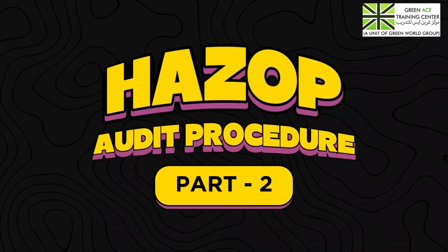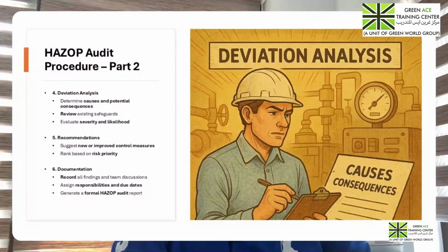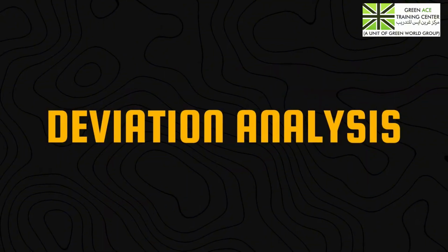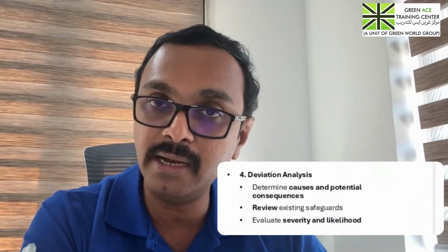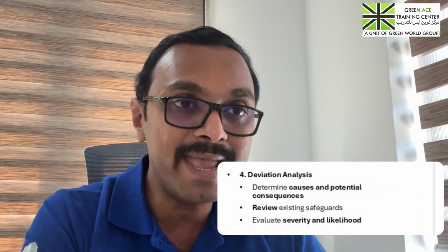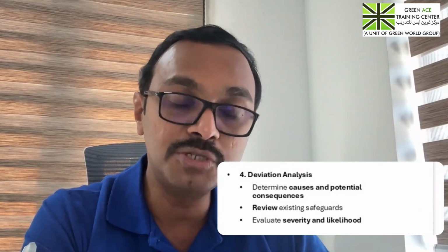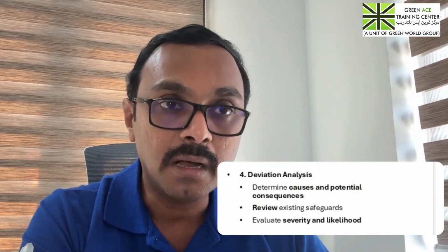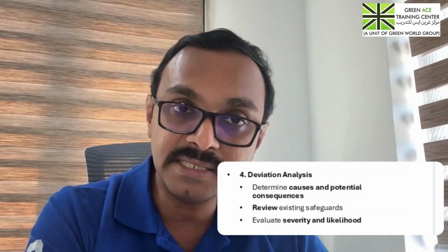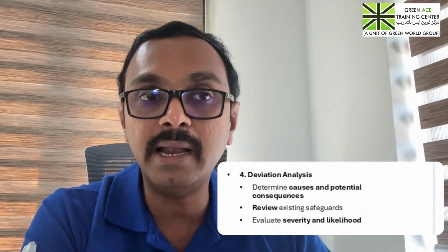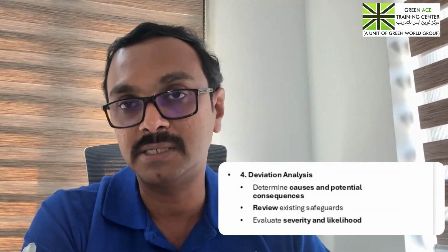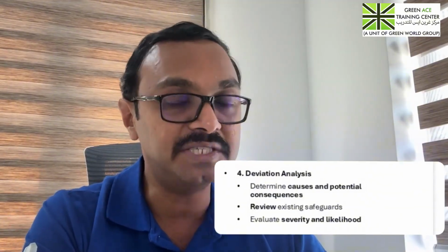Now let's go to part 2. In part 2, we have the fourth step, which is called deviation analysis. What is a deviation analysis? For each deviation identified using the guide words, we determine its causes and potential consequences. We also check what safeguards are currently in place and assess both the severity and likelihood of each risk. That's what we do in a deviation analysis.